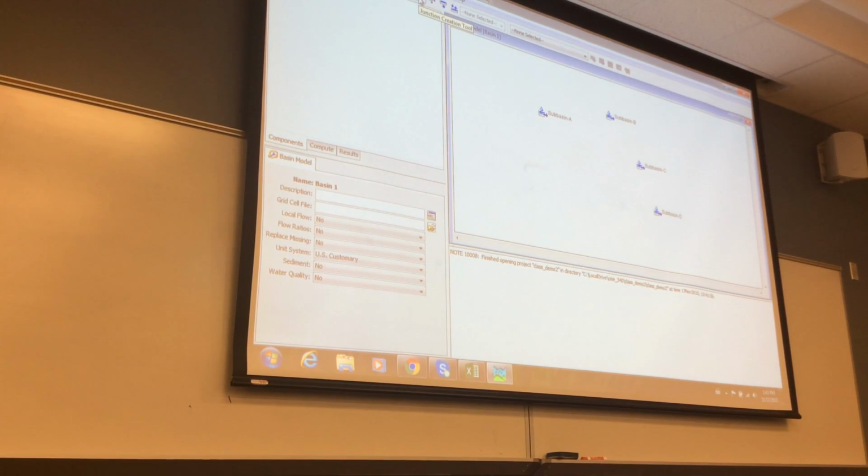We'll also need this one. It's called the junction creation tool. There's a bigger arrow. Not sure how to describe it. It's the fourth thing here, this guy. We will need a junction to put these two hydrographs together, and a junction to put those hydrographs together. So we need 2 junctions. So I'm going to add a junction here. I'll call it junction 1. I don't care. And I have another junction here. I'll call it junction 2.